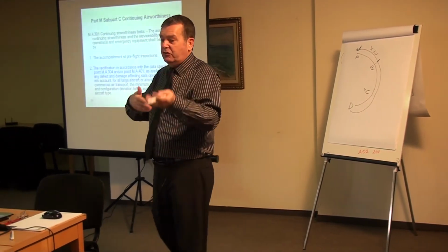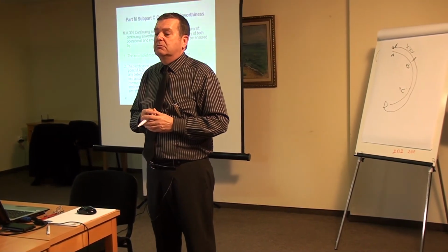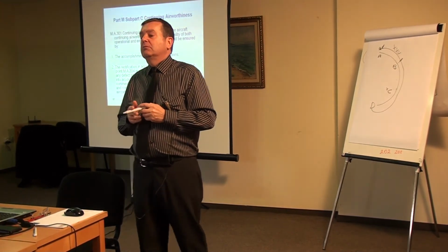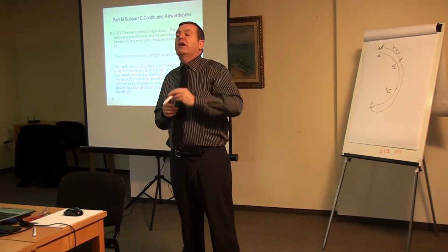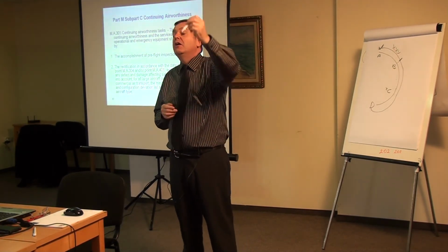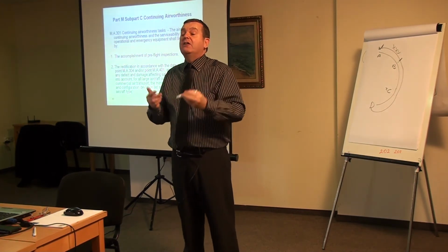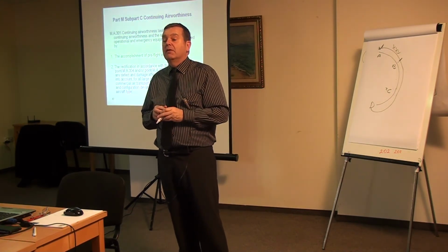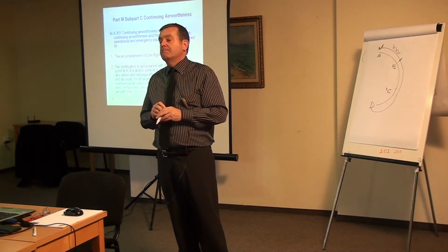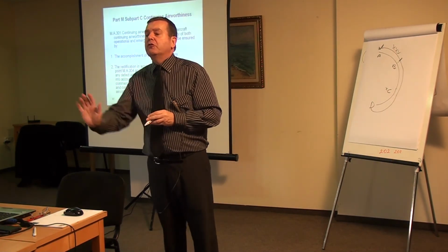Again, I will share stories with you that are in the public domain. Turkish Airlines, 3 years ago. They had an airplane going into Amsterdam. The airplane was at 2,000 feet. There was a defect on the radio altimeter that was not written in the logbook. The defect caused the airplane to think it had landed, and the throttles retarded automatically. And the captain, not sure what was going on, pushed the throttles forward.